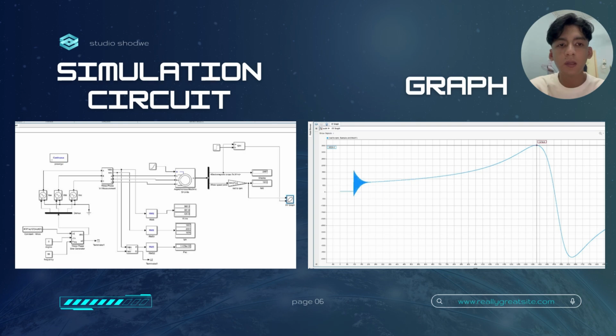I continue with the simulation. The simulation circuit is the same as in the other tests, test 1 and test 2. The difference is that we add the graph, and then we can get the values of V line, I line, and PSC. For the V line we get 382.3, I line we get 1857, and PSC is 1.429E+06.